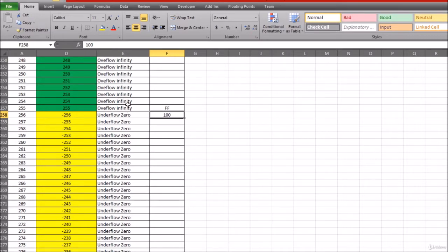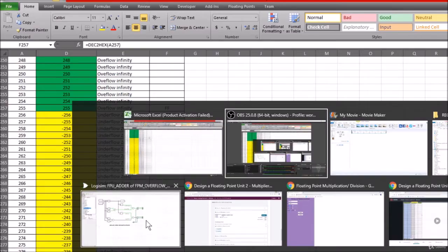As long as it's less than that here, then we know we're going to have a positive value. Now in order to test and find out whether we've got a negative value as well, the negative values are going to start at this point here, which is at 256. So we just need to test and find out whether we've got values that are going to be greater than the 255, which is the FF. So we can just use these in order to make the test, and that's what we've done here in Logisim.